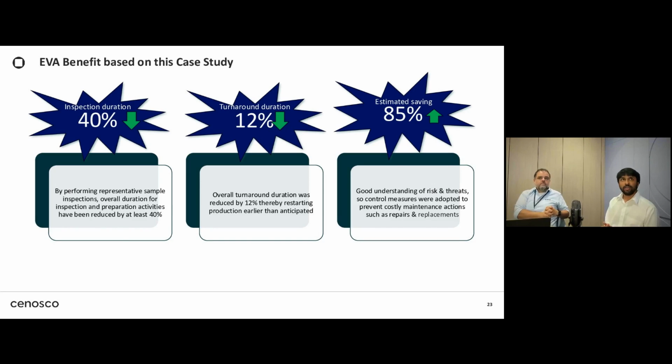Yeah, definitely. So the remnant life, just like what we highlighted, we're closer to 10 years. But if at all your corrosion rates were bound to increase, there were other operational mitigation actions identified. It was a crude preheater, so injecting corrosion inhibitors to reduce your expected corrosion rates could lead to longer remnant lives and things like that. So of course there were other potential actions in the back of the customer's mind, but overall that was a lot better than completely replacing the bundles.